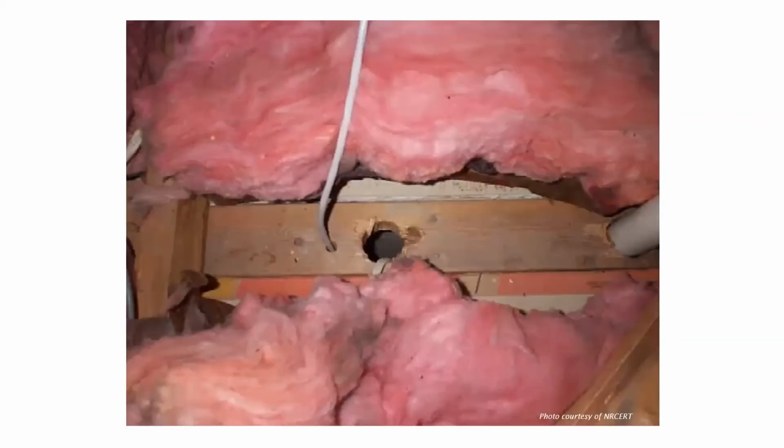This picture gets me every time. Looks like an opportune electrician took advantage of an inaccurate plumber. Maybe I'm wrong, but it looks like the plumber drilled in the wrong spot or decided after the fact to move the pipe that you can see on the right. Later, an electrician ran some Romex down the big hole because it was there. No matter how it occurred, it's a large hole in the top plate and will allow for excessive air leakage through that stud.